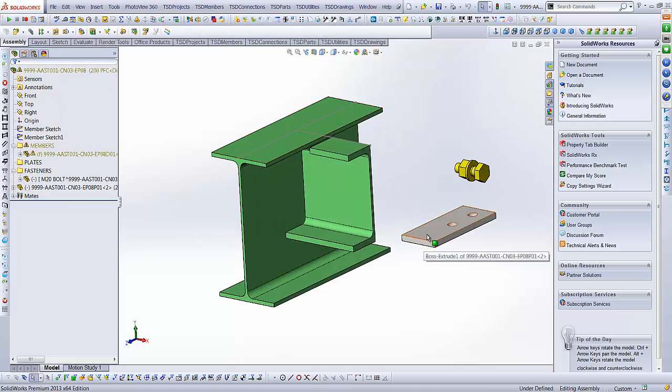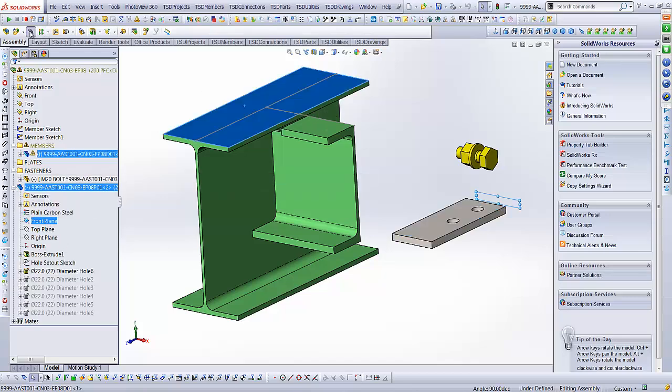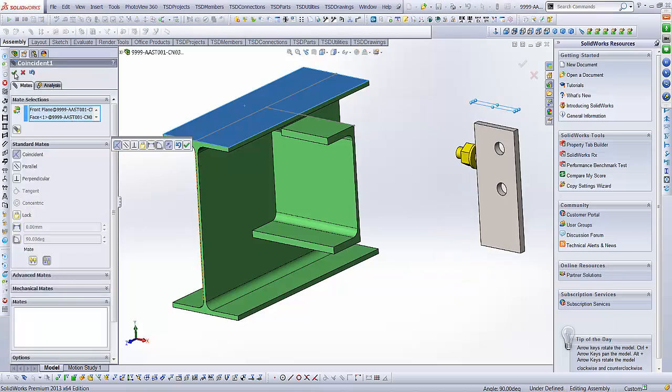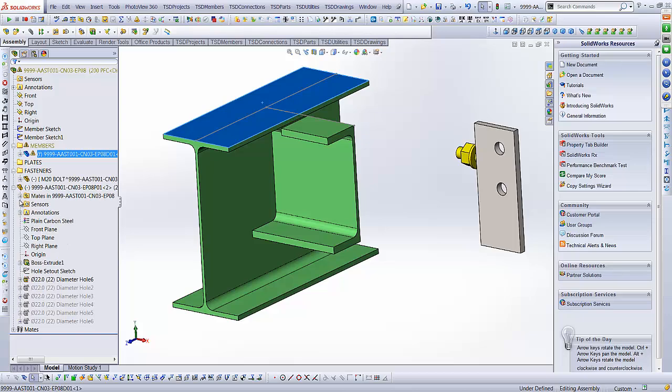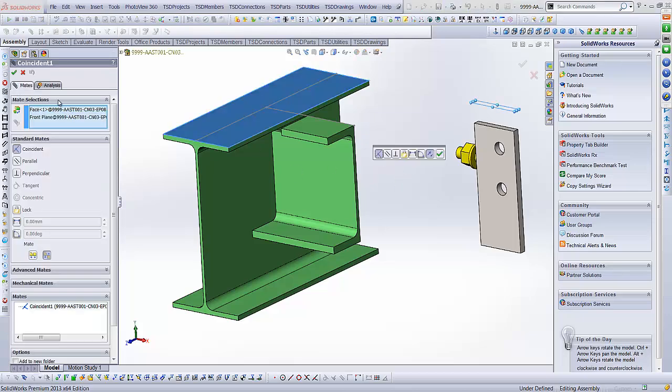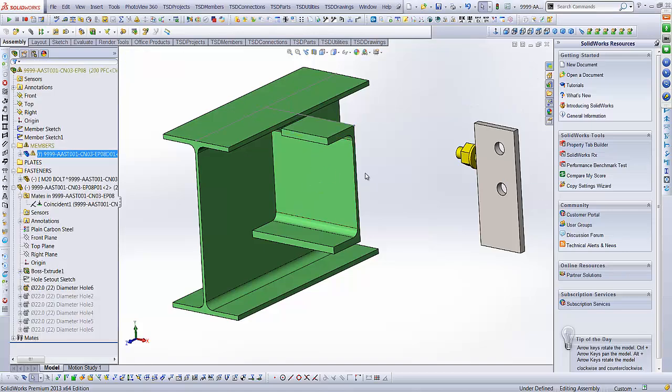Now what I want to do is position this plate so that it's hard up against this face. And I also want to set it down, and it's already got a set down in the plate. Now I made that mated to that, and that's incorrect. I'll just change that again. I don't want that face, so I'm going to remove that face. I want to mate it to this face, because if this section happens to need a requirement to drop, then I've got the whole thing mated to this and it'll move with it.